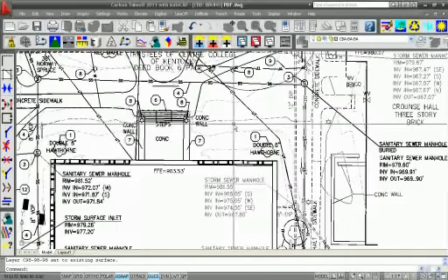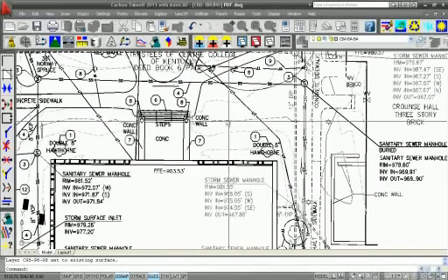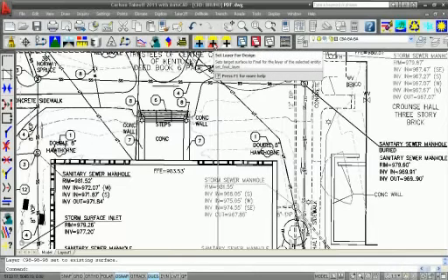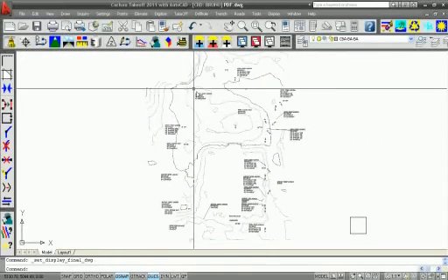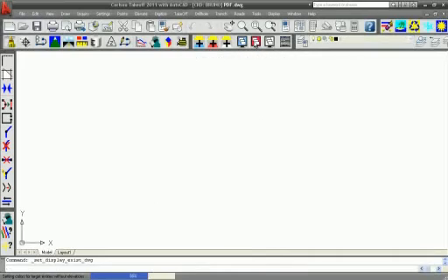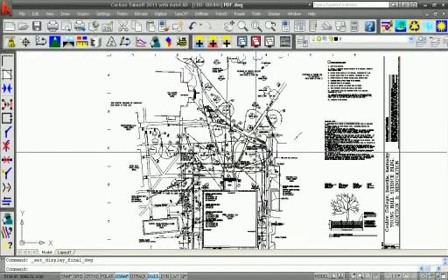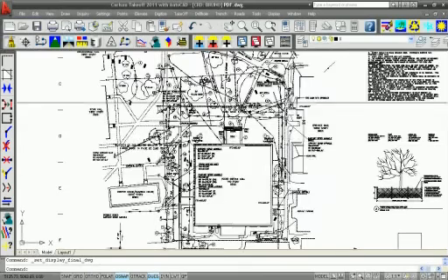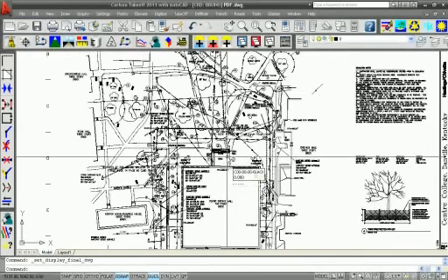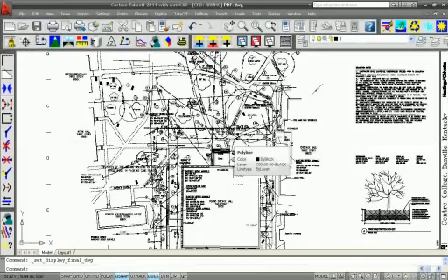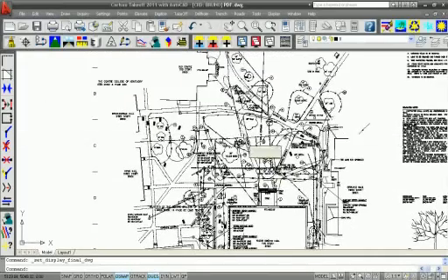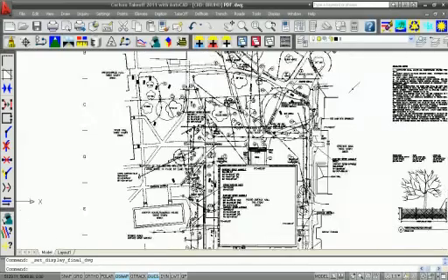Because obviously from that file we need to find out what the existing is and what the proposed is so we can get the differences. Right. So it's important we find which layers, which line work, is attributed to which file format, whether it's existing or proposed. Okay. So I have some line work under existing now, and some line work under the design. Now, obviously, there's more cleanup to do, but that new feature in 2011 definitely helps you get started. And the more detailed the PDF might be, the more colors it has, the more useful that routine will be.